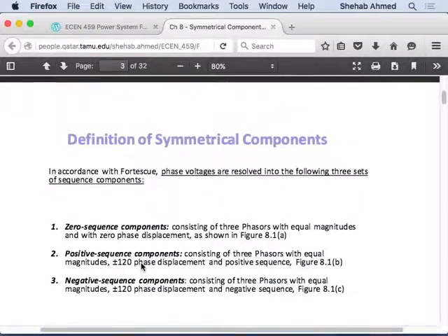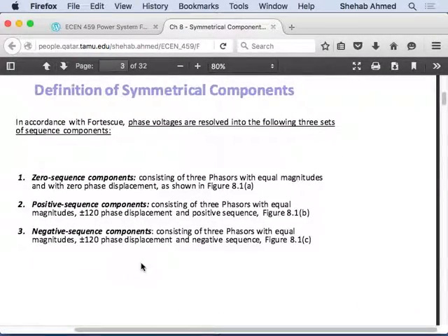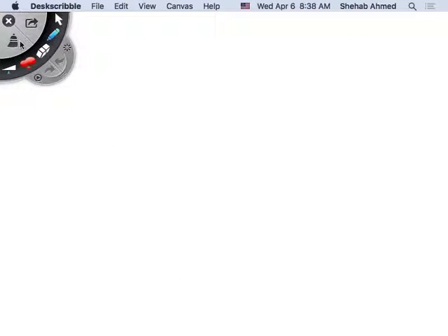Okay, so symmetrical components. What symmetrical components theory basically tells us is the following. Anytime I have an unbalanced voltage or current, meaning I have an unbalanced voltage source or an impedance in my system, I can take the corresponding voltage and current waveforms and chop them up into 3 different kinds, right? So I can chop them up into what is called a positive sequence, a negative sequence, and a 0 sequence. So what does this mean?